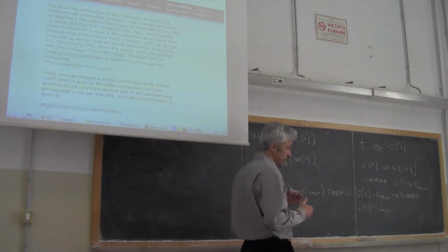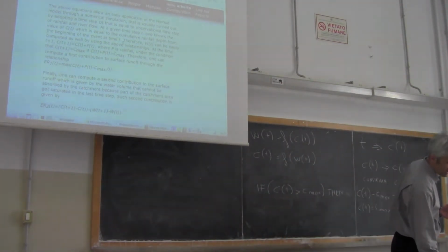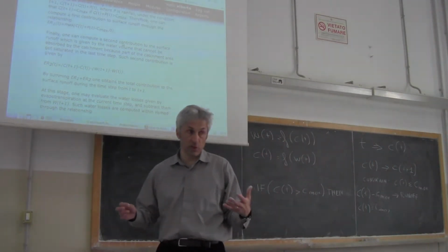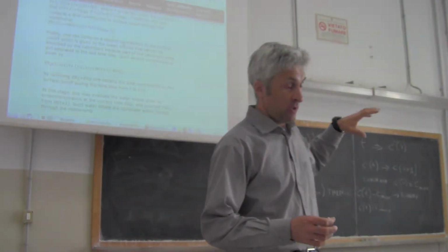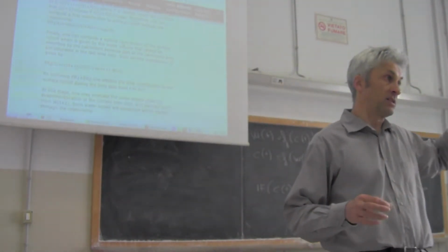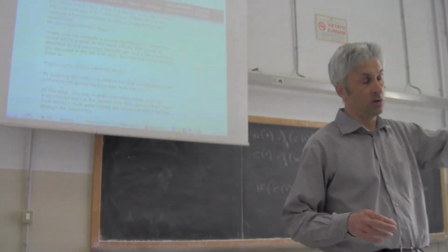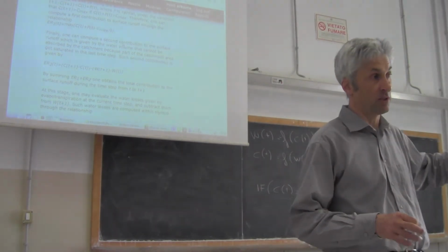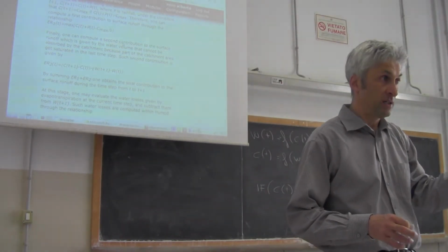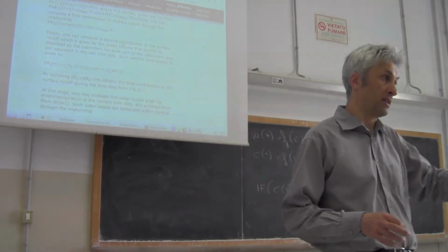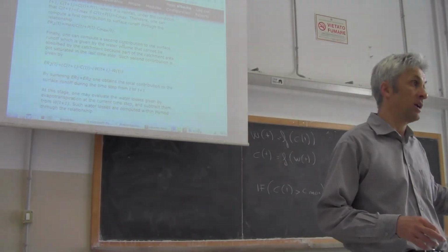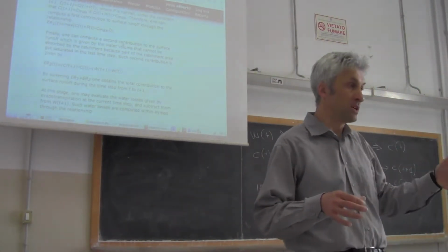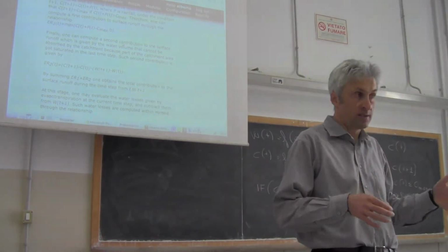But even if Ct is lower than Cmax, I may have a contribution to runoff, which may come from locations in the catchment that get saturated. Remember that Cmax is the maximum potential storage in the catchment, but there are locations that have a lower storage, like impervious ones. Whatever rains over impervious, impermeable locations is transformed into runoff.